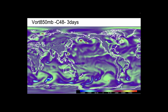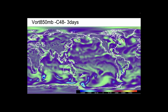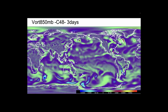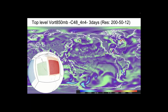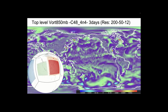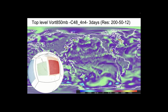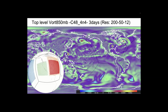So let's step back and look at a 200-kilometer simulation. The field you are looking at is the vorticity at 850 mb, and you can clearly see that the hurricane starts here and then spins up very quickly, even before reaching land. Then we have this configuration where we add 4 different nests: 3 same-level nests, one over the east coast, one on the west coast, and one in the Pacific, and 1 telescopic nest, the big red one over the east coast, as you can see in the grid layout.